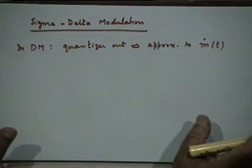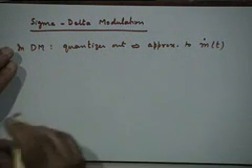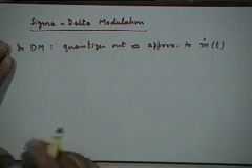Would you agree with this statement? Now, is that a good thing or a bad thing from the noise point of view? That is, if there is any noise, it will get enhanced, right? So, there is a transmission or disturbance somewhere, it will get accumulated because of the fact that the transfer function is omega square, right? Transfer function magnitude square is omega square.